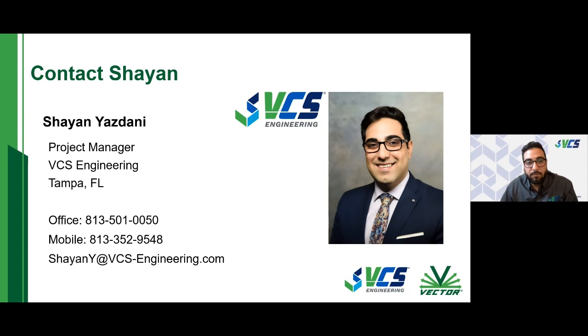Would you also recommend this type of technology in, say, a new construction project? Yeah, we've had owners where, I mean, Florida DOT is at the forefront of that, but also we've had projects out on the West Coast of the United States where owners knew that their structure was going to be in an aggressive marine environment, and they decided to pre-install these distributed anode systems in specific elements of their structure where they knew corrosion was going to happen, and it was going to happen at a high rate.